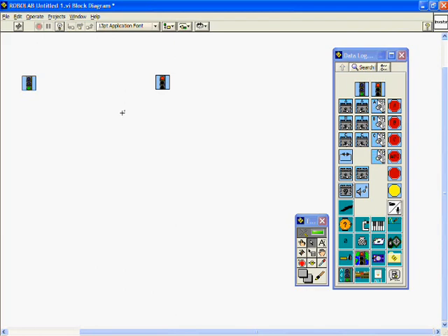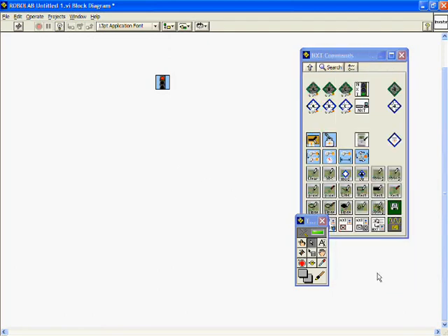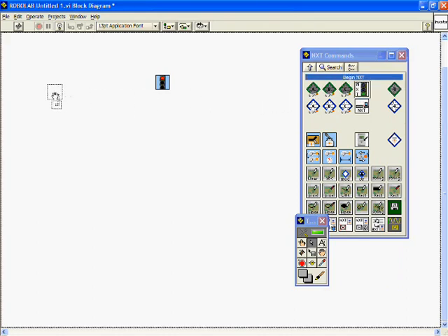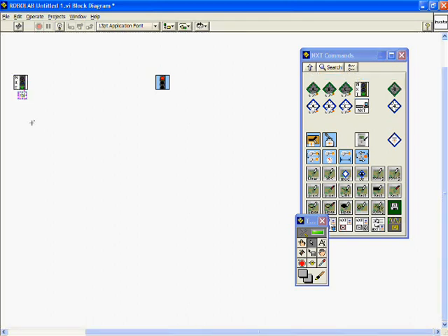Let's create our first program. In this program, we want our robot to go in a straight line and forward for a certain amount of distance. The first step, we want to delete the first green light we have. Then going to our Functions palette, select NXT, then select that green light in this menu. Left click and drag. And now notice, below this green light is a pink box. This is where we name our program. Double click it. I'm going to name the program Forward.